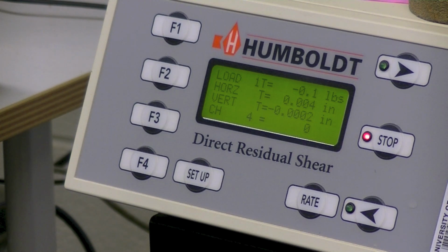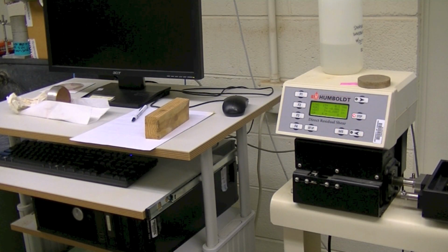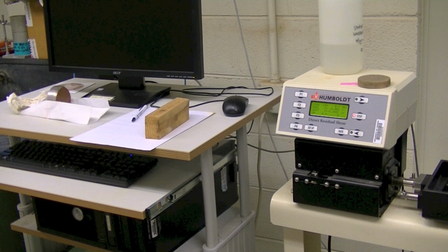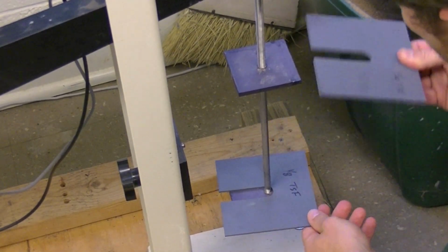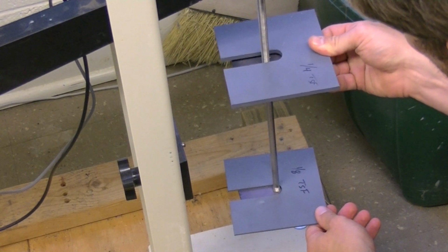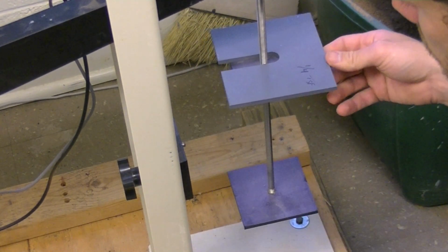Once the secondary consolidation phase is complete, the next load increment is ready. We will later explain secondary consolidation in detail. Stop recording dial readings. Record the first and final dial readings. Place the next load on the carriage while simultaneously starting the clock. Repeat the process for the remaining axial stresses in the sequence.